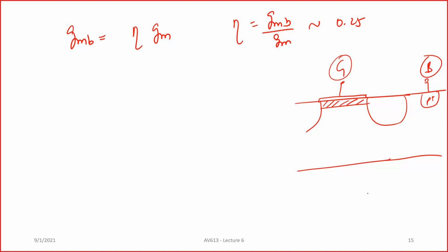In low frequency analog circuits, we don't talk about two tone tests and the 1 dB compression point. We define what is called total harmonic distortion. Basically the same concept, it's just that it is typically expressed as THD.